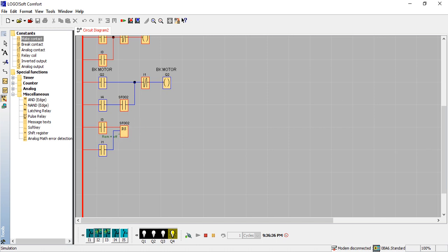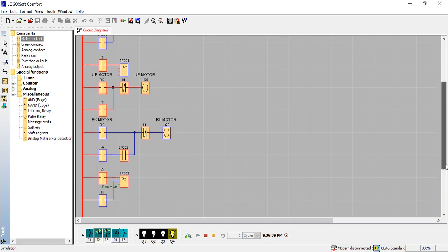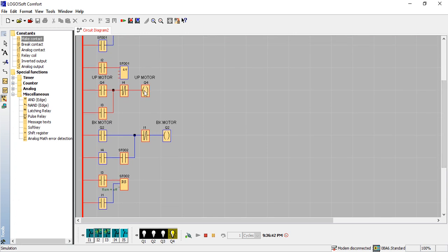Now we're going up. Q4 is activated. Look at this. Q4 is activated. And this needs to be unpressed again. You see that? Q4 is activated. It goes up until I4 here. When I4 and this signal, the signal that is represented here, match with the current signal at I4, when they both match, our motor Q2 is able to send the product